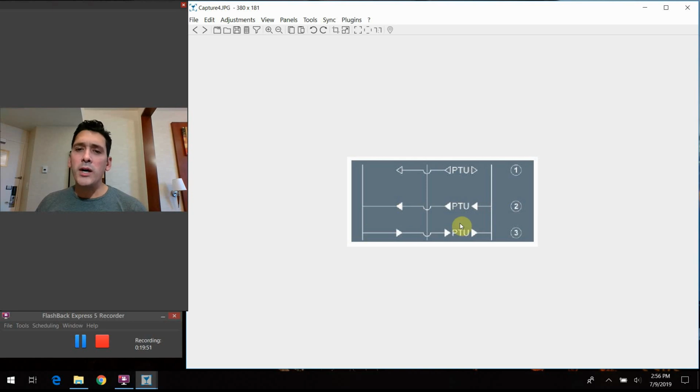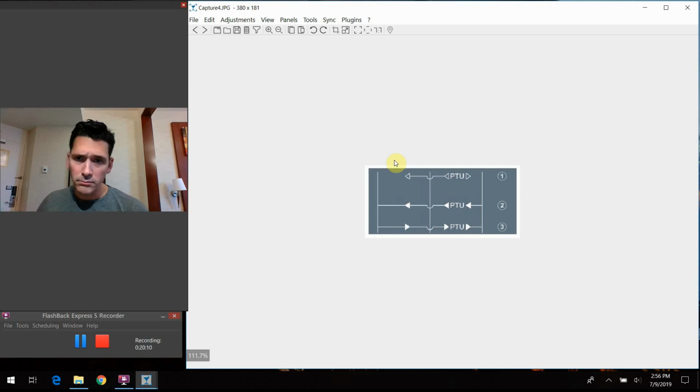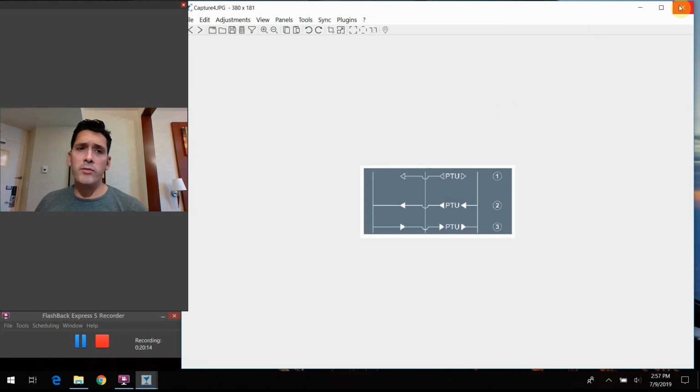And then we have the two contrasting scenarios here, where the yellow system is driving the PTU, which is in turn driving pressure into the green system. Vice versa here, the green system is providing pressure to the yellow system and allowing us to operate all our components as needed for whatever given situation the plane is operating in at the point in time.